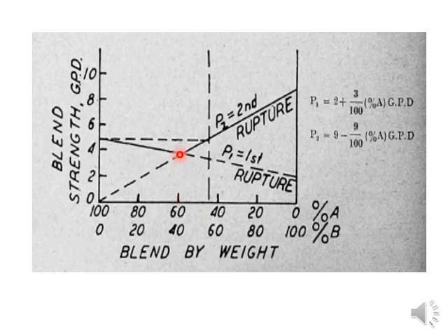So that's why the stress-strain behavior, or the relationship of the stress-strain of the individual fibers of the blend, plays a very important role in determining the tenacity of the final blended yarn. So how this graph is being produced, we will discuss in our video lecture part 2.